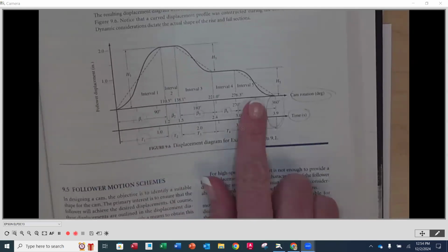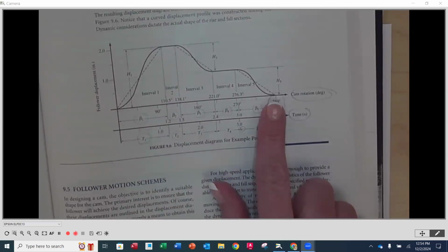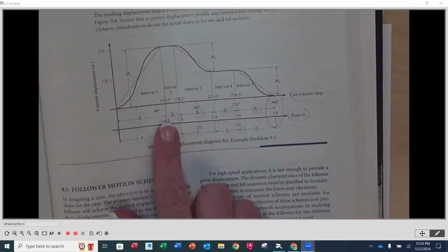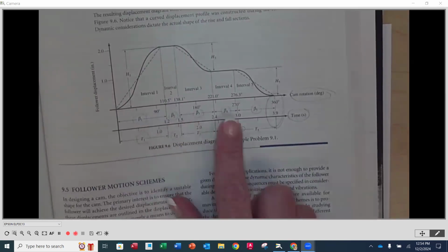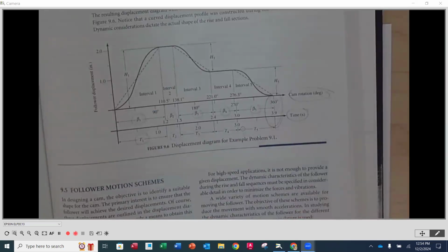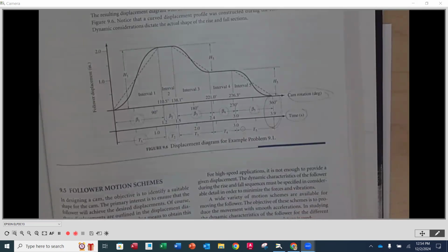But as we look at the x-axis here, do you see where your betas would be for each one of those values? So it's a total of 360 degrees. And then to scale, you would have each one of those values. So the first one was 110.5. Our next one was about 27.6, 82.3, then 55.3, and about 83 is going to be the last. When you add each one of those up, they should come out to be 360 degrees. Okay, if they don't, that's a great check for you to do. Then you did something not quite right.